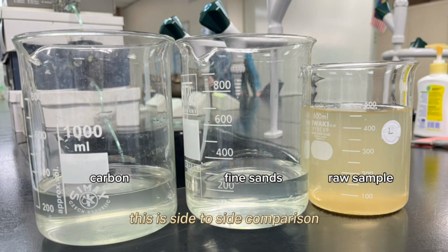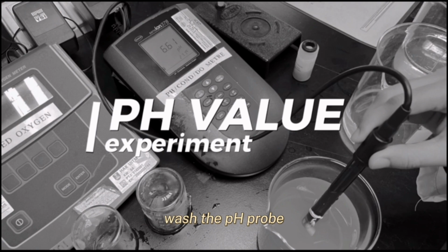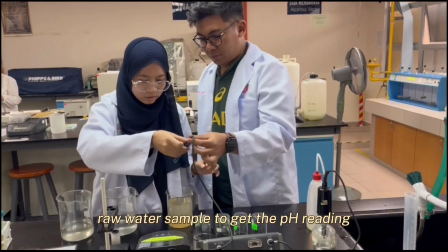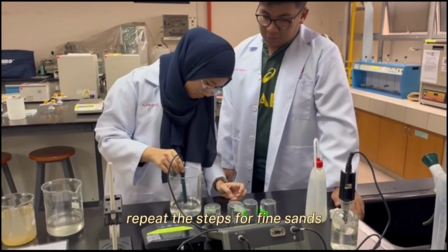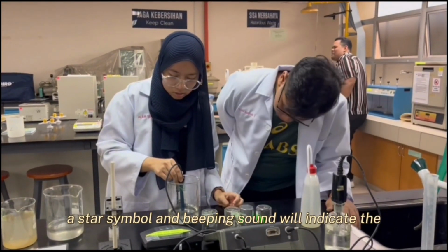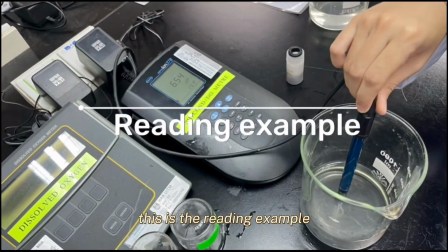This is a side-to-side comparison, where we have the carbon water sample, the fine sands water sample, and the raw sample. First parameter is pH value. Wash the pH probe with distilled water and insert it into the raw water sample to get the pH reading. Repeat the steps for fine sand and fine carbons water sample. A star symbol and beeping sound will indicate the pH reading has been obtained. This is the reading example.